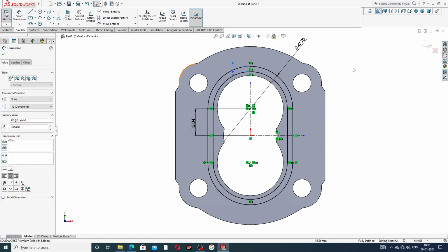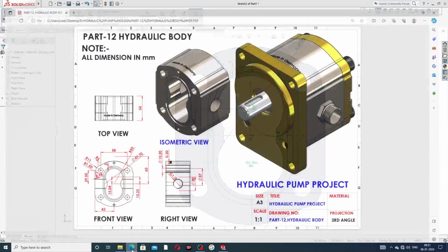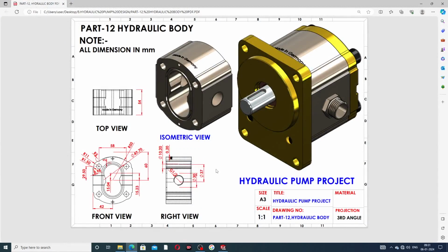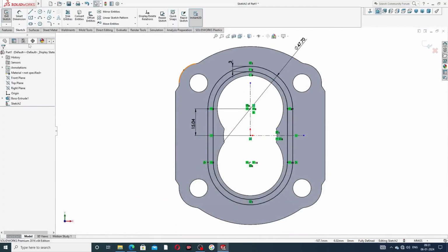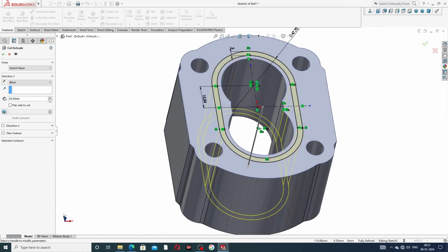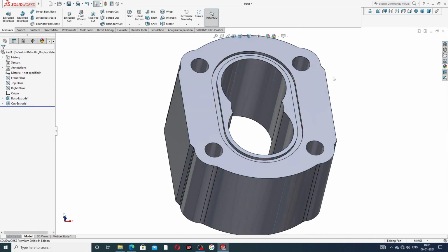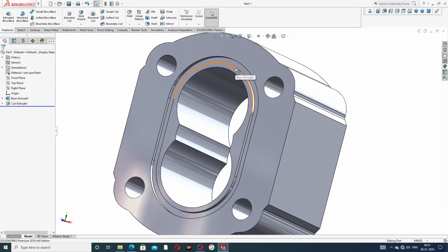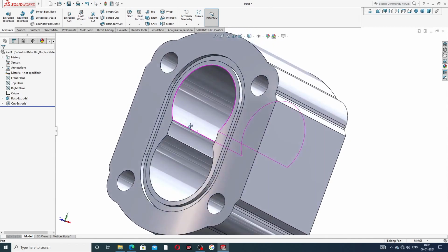This offset is used here, and the cutout is only 2 millimeter, which is not mentioned here, but it is a 2 millimeter cut. Use extrude cut, only 2 millimeter because this is a rubber belt. Click OK. A rubber washer is used here, very nice looking.